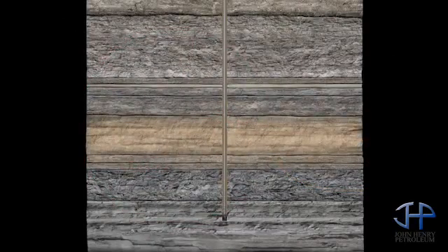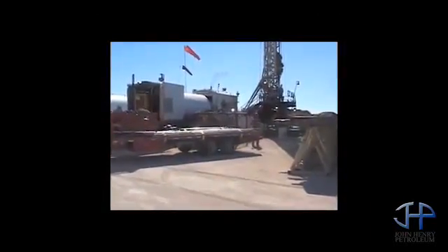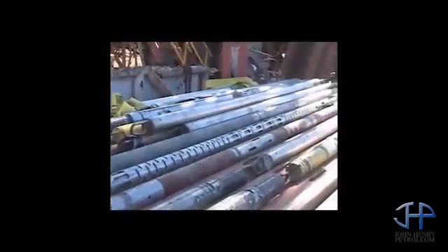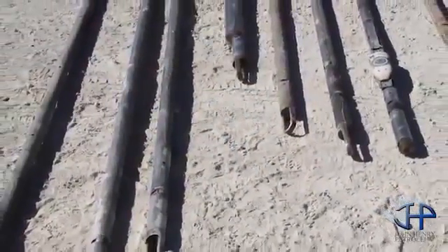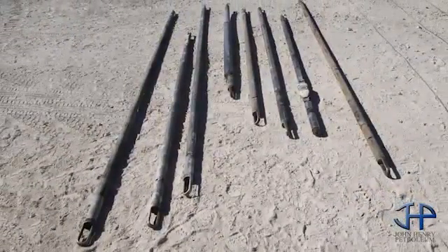Once the well has been drilled to its target depth, the drill pipe and bit are removed from the hole. A specialized logging crew and equipment are brought on location. The crew assembles a probe, which is several different logging tools connected together. Depending on the number of tools in the assembly, the probe may be 70 to 120 feet in length.